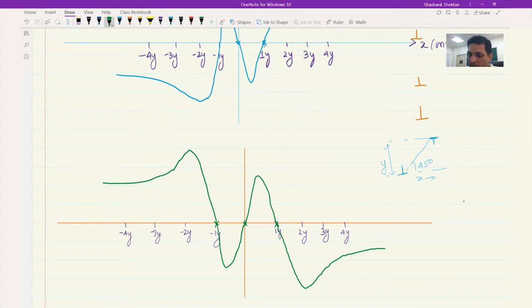So what it means is that if you are at 45 degrees, then of course it is equilibrium, although in the previous case we saw it was an unstable equilibrium. Now if the dislocation moves a little bit to the left, somewhere over here, what will happen? There is a positive force acting on it. Positive meaning in this direction. So the forces are trying to bring it to this position.